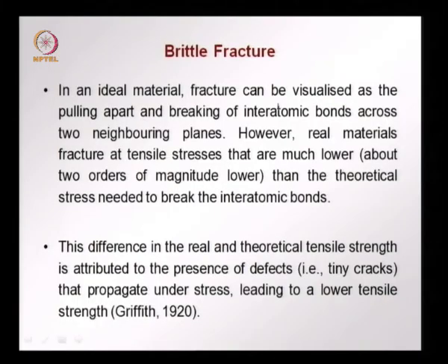Ideally, we have fracture occurring with the pulling apart of bonds in neighboring planes. However, we will see later on in more detail that real materials fracture at tensile stresses that are much lower. This is the problem. The failure under fracture occurs at strengths that are much lower than the theoretical tensile stress that should occur when interatomic bonds are broken.